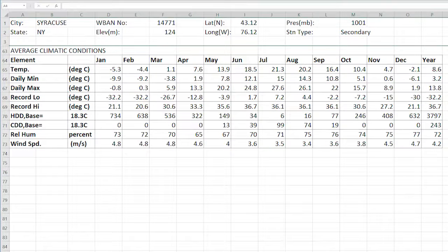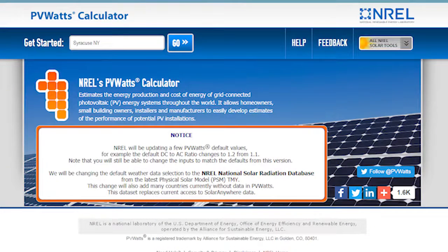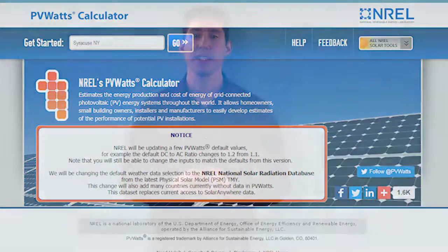Weather information is the last piece included in the solar database because these are recorded at meteorological stations across the United States. Once we have a little bit more background, we can also start using the PV Watts tool that's available through the National Renewable Energy Lab. And that begins with entering a location and inputting a system size. From there, the system can automatically calculate the expected energy a system will produce with variations in tilt, rotation, and other losses. In the next segment, we'll look at how photovoltaic energy from these data sources can be used to actually design a system from insolation through to output energy.